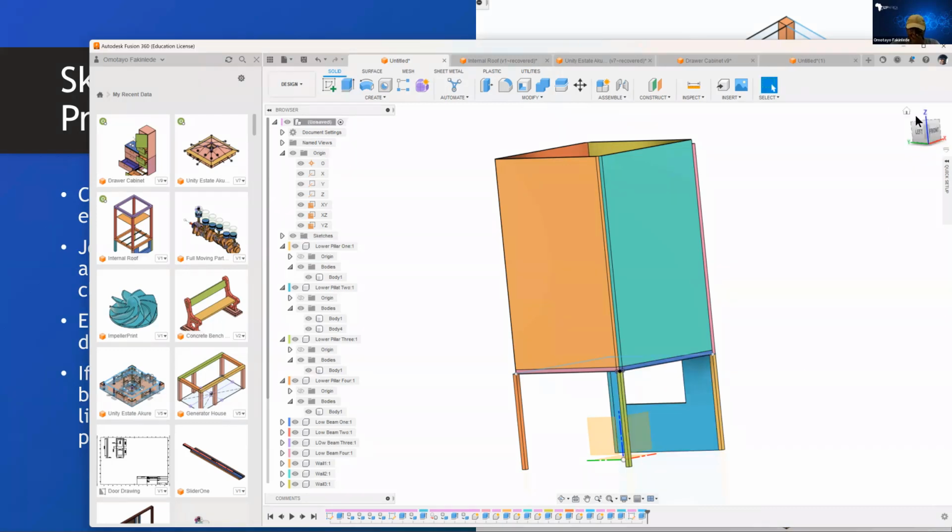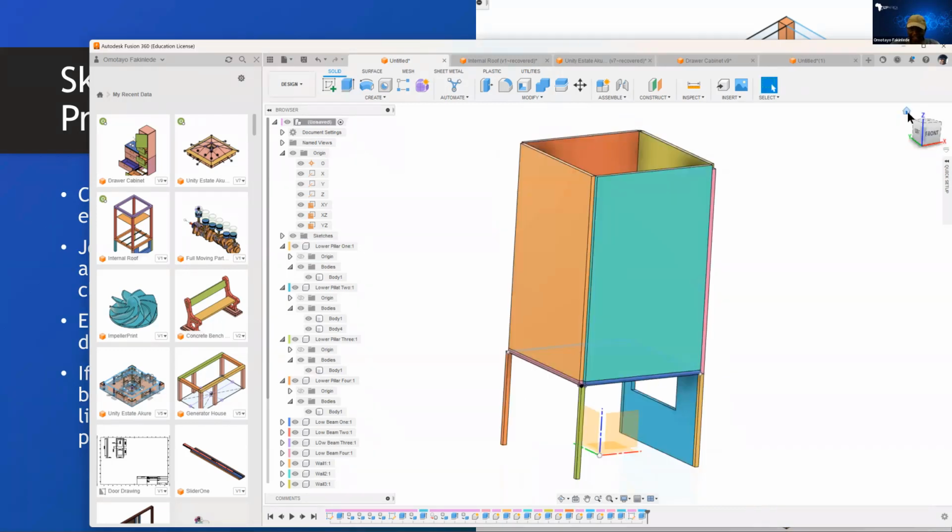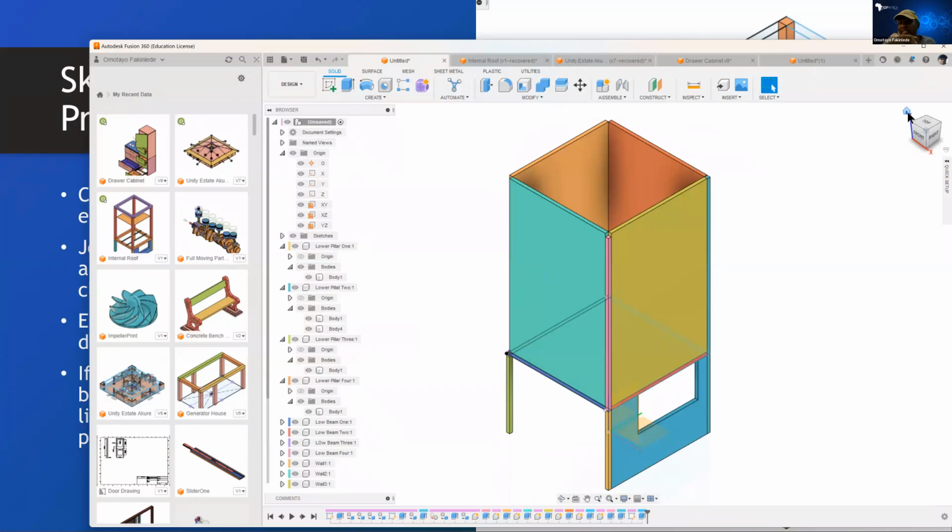You can see this is much more satisfying than having to know what the distance is. If there is an object already, so I am starting an extrusion from this profile plane. I want to do it to the end, to the other side. So all I need to do is to choose the object of the other side. Once I click any part of that other side, that extrusion will take place. And